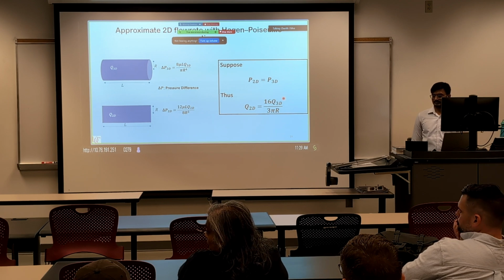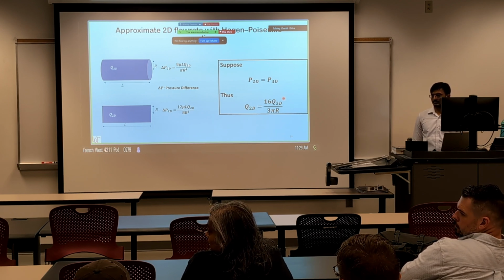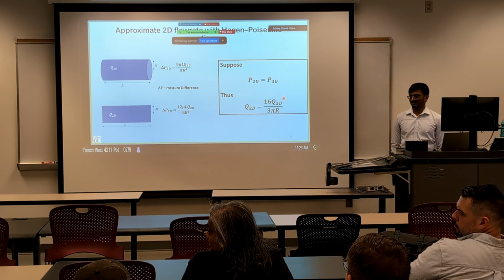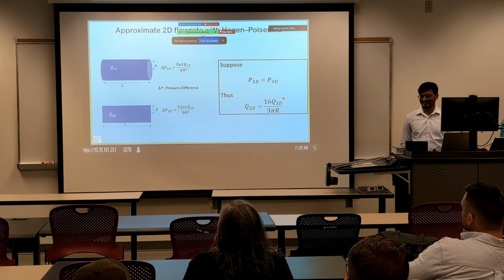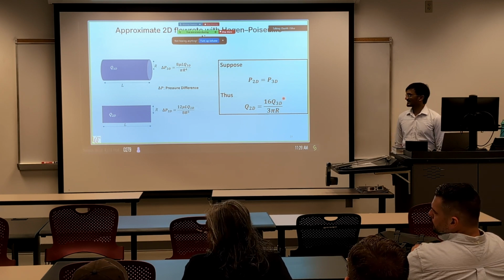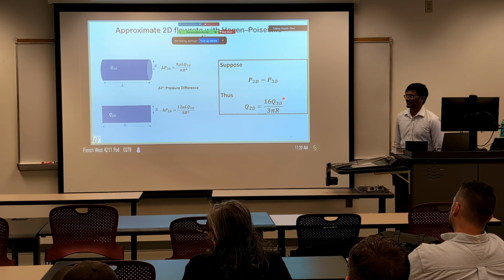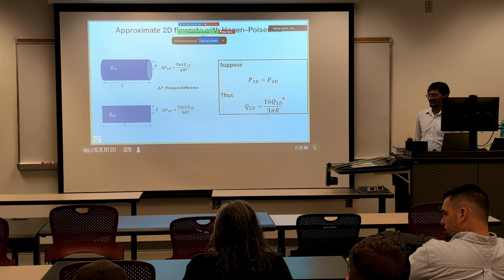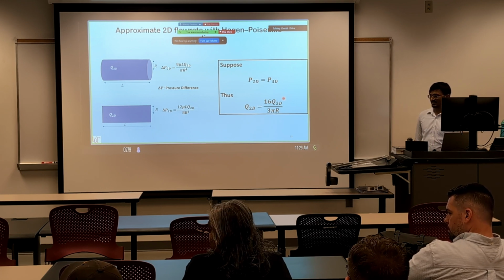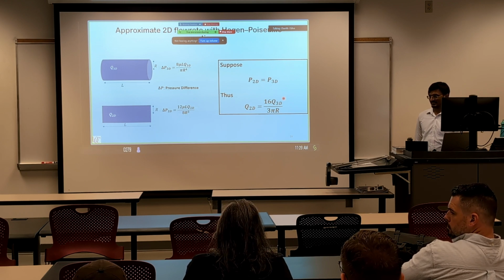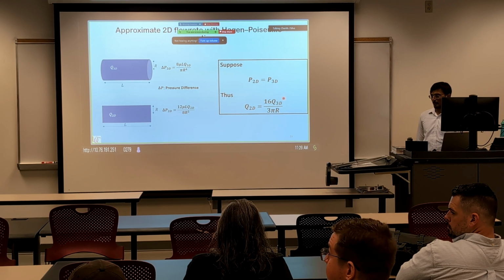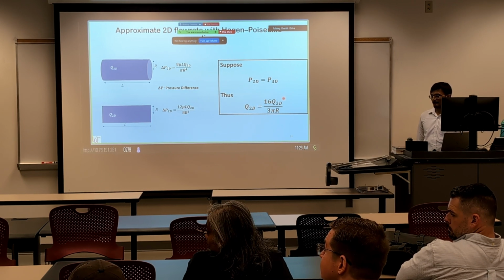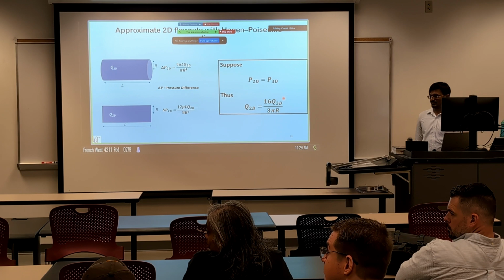So what you're saying is it's actually a transformation of the equation. It's a very creative assumption to find a solution that turns out to actually work. But there's an R in that bottom equation. Yeah, he defined R as the half height of the 2D. Right, but you said that Hagen-Poiseuille is a 1D thing. Yeah, the pressure drop varies only in the axial direction. The fluid velocity varies in the perpendicular direction. In 2D, it would be the vertical direction.